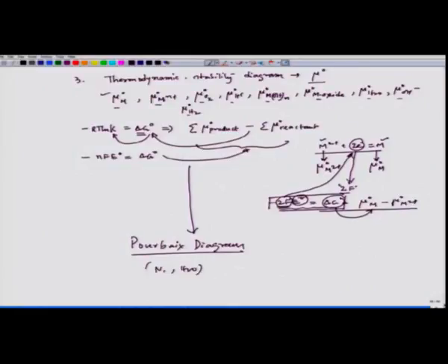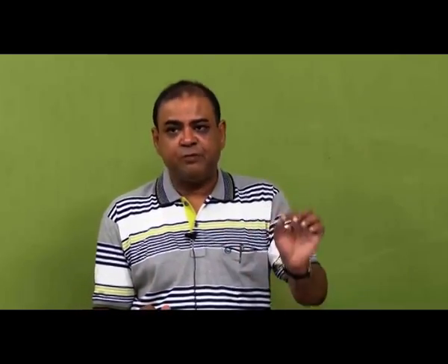So, in our next lecture, we will try to work out one example in the nickel system, the nickel H2O system. We will try to see the Pourbaix diagram, and we will start from the chemical potential of different species, and we will end up getting that diagram. Then we will see that yes, in this position, I will get metal remaining as metal. In this position if I go, I will get metal ion formation or corrosion, or in a certain region we might get metal hydroxide which will settle down. So, we consider it to be a passivating zone.